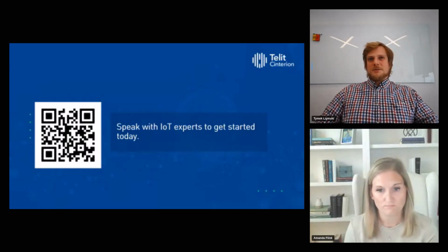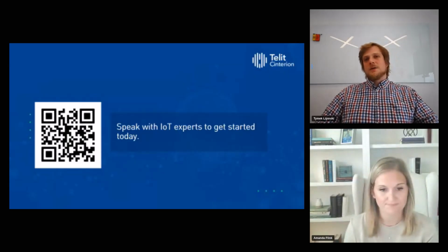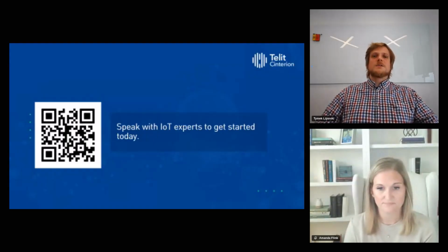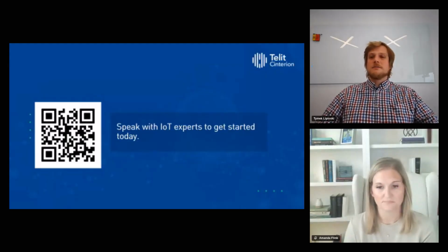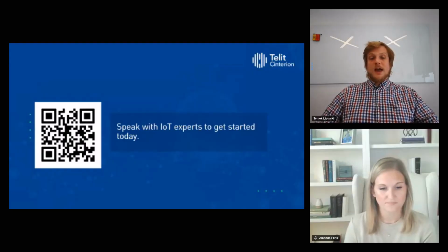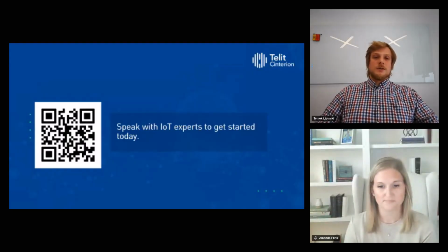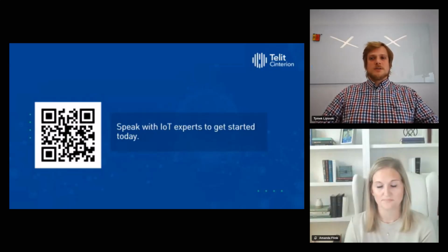So the key trade-off here between CAT-M and NB-IoT is the mobility issue. CAT-M is designed to support moving between cells, between base stations. So it's still suitable for tracking, let's say, vehicles, bikes, people, dogs, cats, and so on. On the other hand, NB-IoT was designed to support only stationary devices.